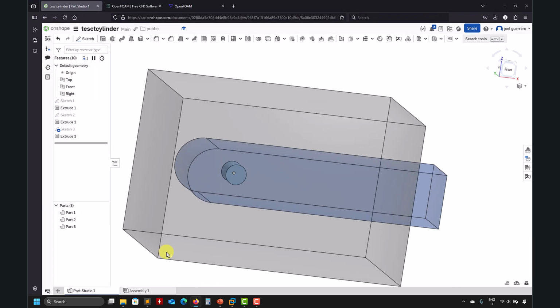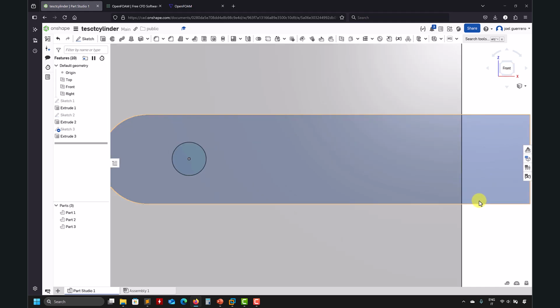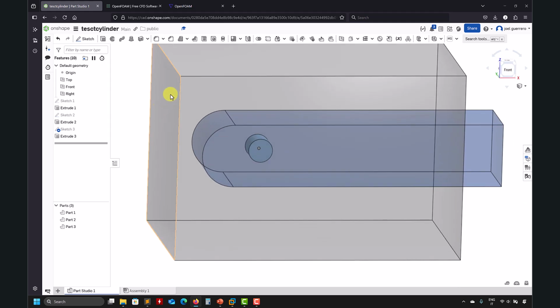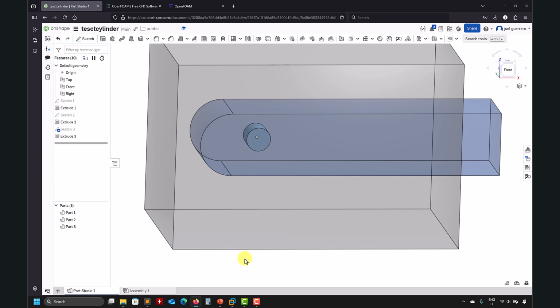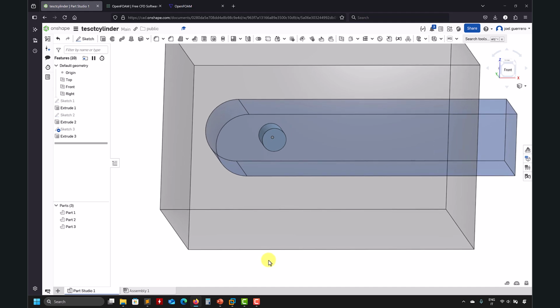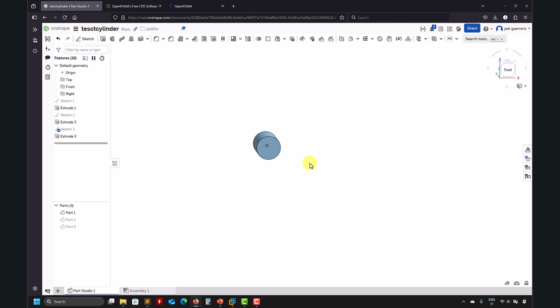So this is how I do it. You can see the importance of having the geometry. Now that you have this visual reference, you know the extremes, the coordinates of your domain, you can export different boxes, you can see the smallest edges. Sometimes you do the mesh and you see that you have a problem in a particular region, you can modify that, you can add a fillet there and so on. So there is a lot to do. I recommend you always do the geometry, spend some time.